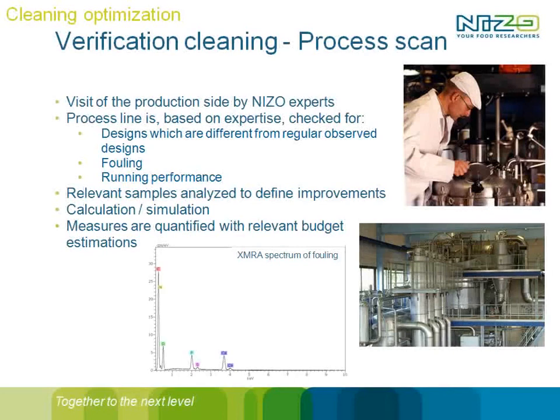We've optimized our process, we've optimized our cleaning procedure. One thing remains: always check it from the inside. For example, evaporators, well, they're nasty pieces of equipment, a lot of dead corners, spots which are not cleaned very well. Really look inside whether everything is clean, yes or no.